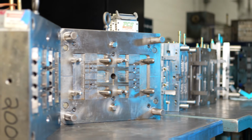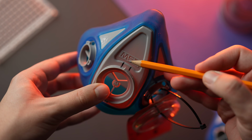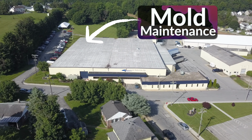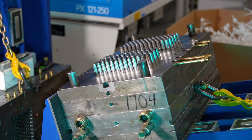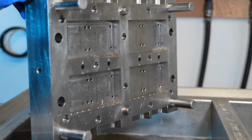And then of course, flash can simply be caused by a low quality or worn down tool that no longer fits well together along the parting line. Crescent remedies this by having our in-house mold maintenance department just a few feet from our general production floor, allowing us to regularly clean and maintain our molds before this sort of thing becomes a problem. These are certainly not the only causes of flash, but some of the most common for sure.